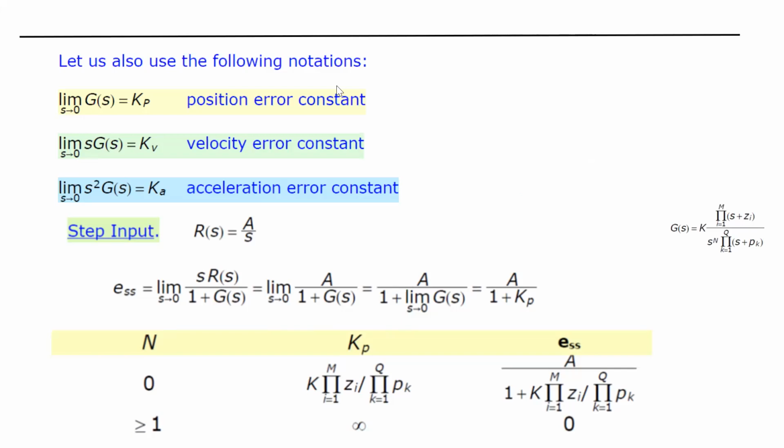Like, you have many poles. The system will be unstable maybe. Possibly, yes. I'm adding more poles at the origin. If you add more poles at the origin, your system might go to the instability region. So there is a compromise. You cannot just keep adding poles. That's also not good.